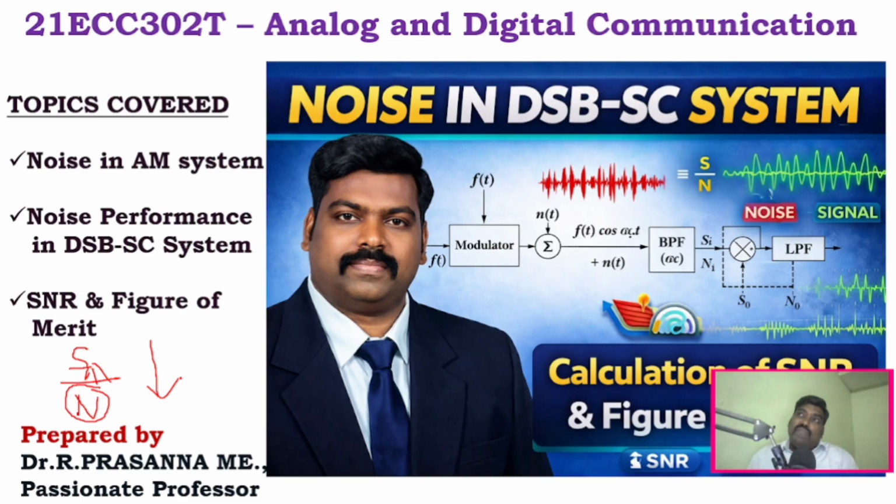And what is figure of merit? Figure of merit tells you how well the complete system, a complete DSB-SC system or an SSB-SC system, handles the SNR, how it maintains the SNR. That is, figure of merit can be defined as SNR output divided by SNR input, which means how well the system maintains a constant SNR, right? How well a system maintains the SNR, that is called figure of merit, right?